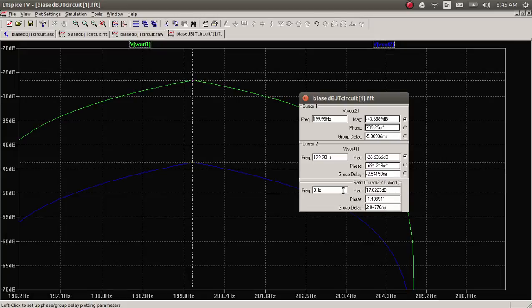Again, what we are looking at is the delta. It's almost 20 dB, almost 10 times as clean, or 17 dB, so around 14 times as clean as the other waveform. So the second harmonic is so much smaller in the cleaner waveform. It gives a sense of how the harmonics work. And distortion is another important aspect of the design.